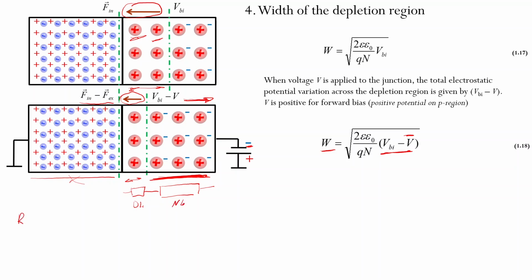So our depletion layer resistance is much larger than our neutral layer, and that's why all external potential difference which we apply will drop over the depletion layer. So that is what happens when we have forward bias.